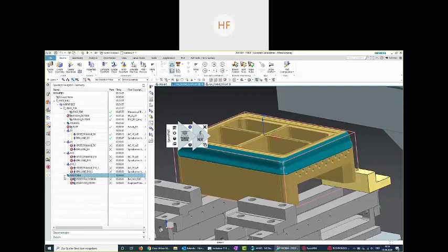It's called pockets. Double clicking on it, I see that the floor, or the bottom, is already selected. I just have to add another trim boundary in it. The trim boundary will be around this face. By saying okay, I can also check out the slot geometry. Previously it's been in this cross manner, but now I have the circle only. Right click on the slot, generate.